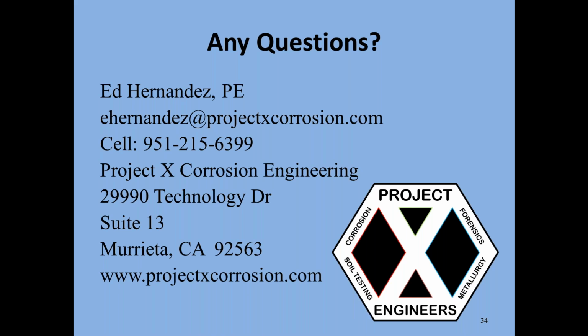It's tough because some people take the approach that the corrosion rate of a pile underground at a site is calculated in a way that the steel will not start to corrode until all of the zinc coating is consumed on the outside of the underground portion of that pile. And that's not how nature works. Usually it just starts at a spot, and once maybe 3 or 4 inches of galvanized steel has been removed from an area,